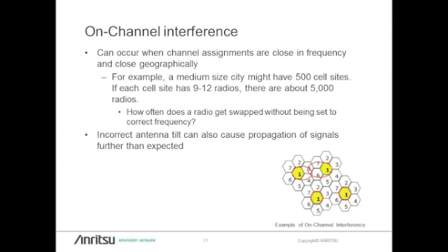So you're looking at somebody deploying these systems in a mid-size area where there could be hundreds of cell sites, and say each cell site is multi-sector, 3 or 6 sectors, maybe 4 carriers per sector. You're talking about a lot of different radio systems. So the chances are exponentially larger, in these multi-tiered, deployed systems in cities, that you could have an incorrect frequency or incorrect setup where you're generating interference.